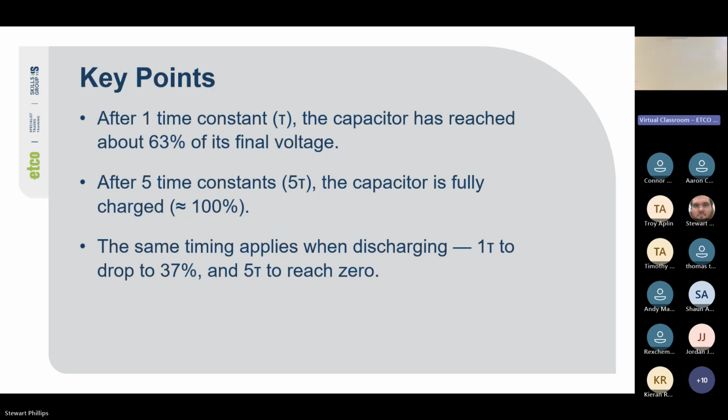So yeah, a capacitor would be a horrible type of storage device for something like solar power, but it's very good for smoothing out DC, because as the AC rippled DC passes over the capacitor, it charges and discharges quick enough that it smooths out the DC waveform. Yeah, batteries are a chemical device. They are not a static device, which is what a capacitor is. Does that make sense to you, Sean, and everyone else?